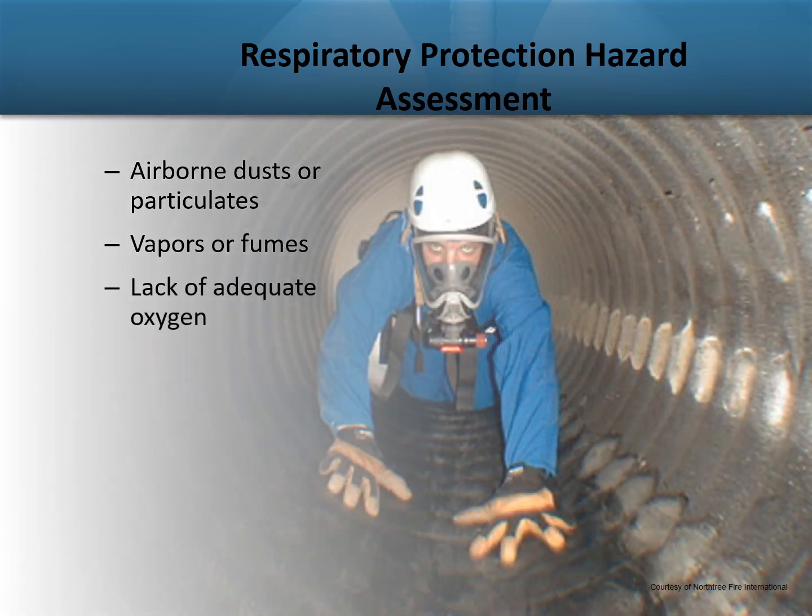Lack of adequate oxygen usually refers to jobs in confined spaces where there might not be enough oxygen to enter without respiratory protection. Think about the kinds of jobs and operations in your workplace that require respiratory protection.